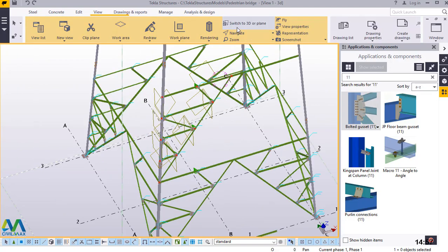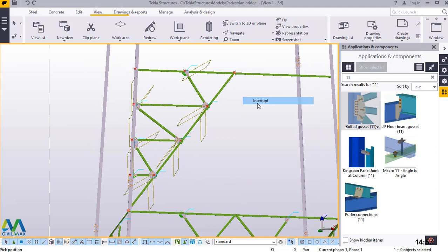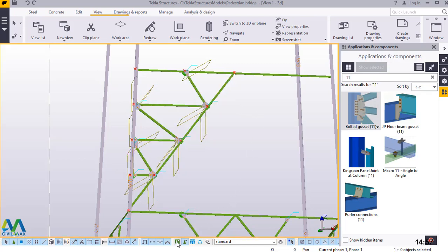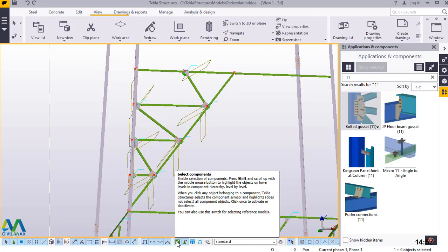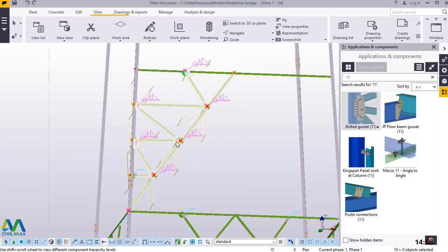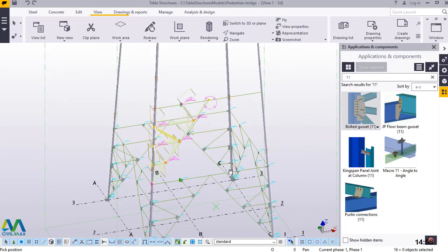Now I'll go back and select my bracings. I'll click that and turn it round. Right click, and I'll select everything here. I'll press Control and pick unselected members. And what I've realized, I've not reassembled my members. I'll enable the assembly so that even my connection gusset plates will be picked. I've selected that, and now the next thing is just to reorient my XY plane.